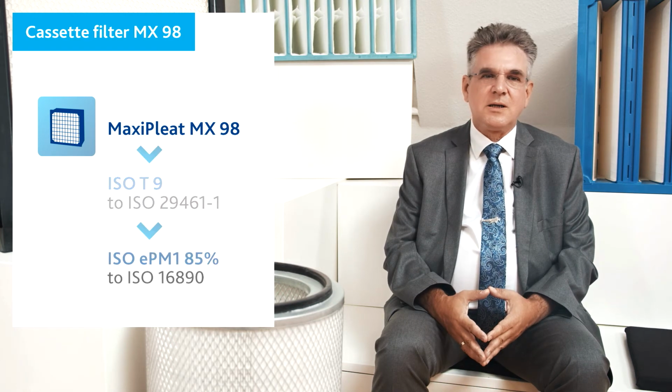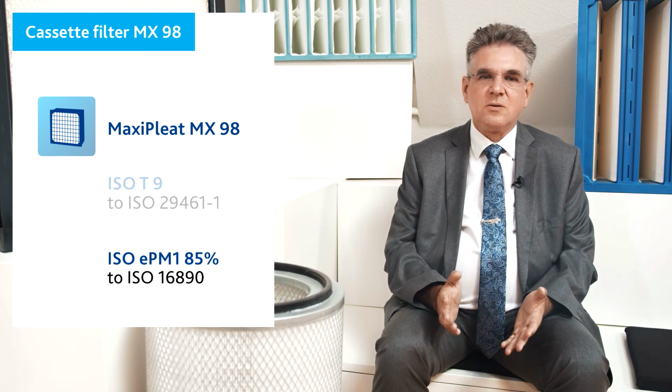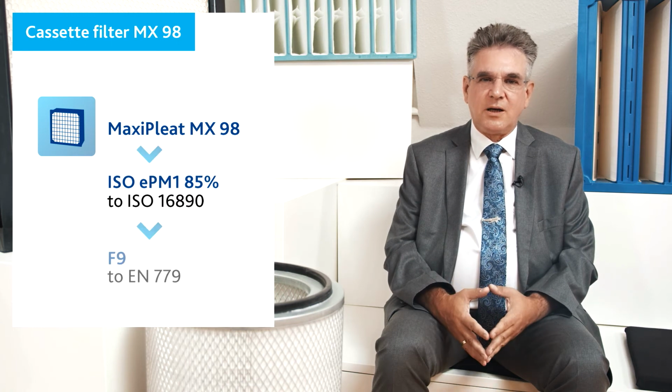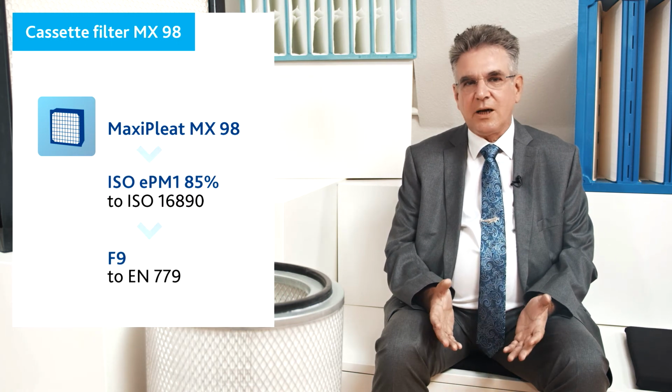With ISO 16890, a new test procedure was introduced which results in transparent filter performance data which are as close to real life as a laboratory test standard can be and which can be directly used for the evaluation of multi-stage filter systems. With the new gas turbine standard, these transparent and accurate filter performance data are transferred into an easy-to-use classification system without losing any information.